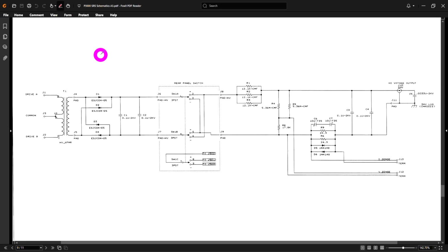They all start from the same fundamental principle. This is still just a DC-DC converter. And then we have a transformer with a high turn ratio. And then there's a drive A and drive B port on this transformer on the primary side. And they basically put a square wave with inverting signals on top of this primary port, and that's going to induce a current, and it's going to get a very large voltage appearing on the other side.